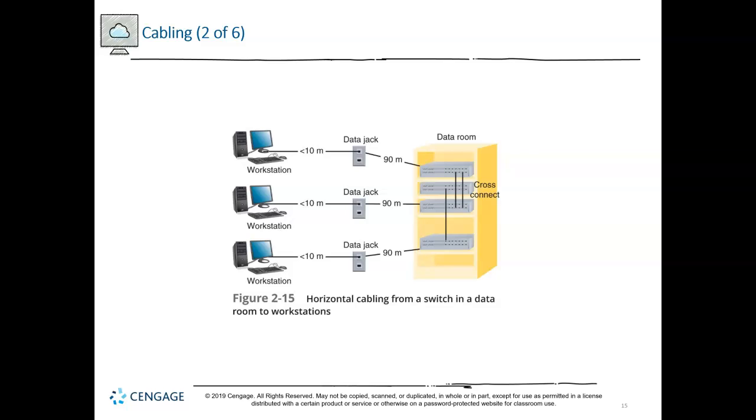Now, does it automatically die at 331 feet? No. And we've pushed that before, and sometimes you can get lucky. Now, when we start getting into 10 gigabits per second on the copper, we start getting shorter distances. And in fact, if we're going 10 gig or above, I'm an all fiber person.